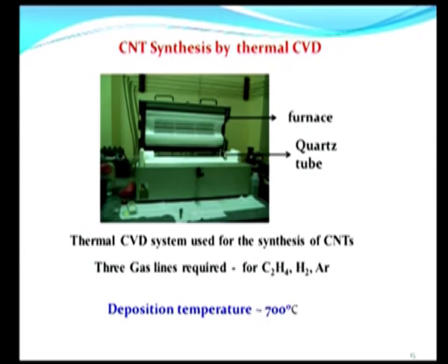This is actually a piece of apparatus, a chemical vapor deposition reactor, thermal CVD, that is, only temperature is used to conduct the reaction, as opposed to something like a plasma CVD, where a plasma is typically employed to accelerate the process.